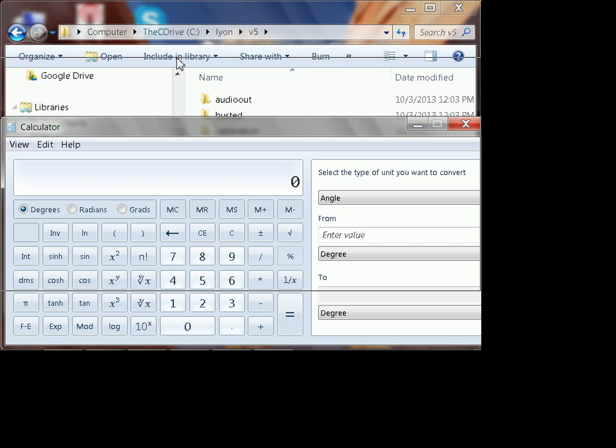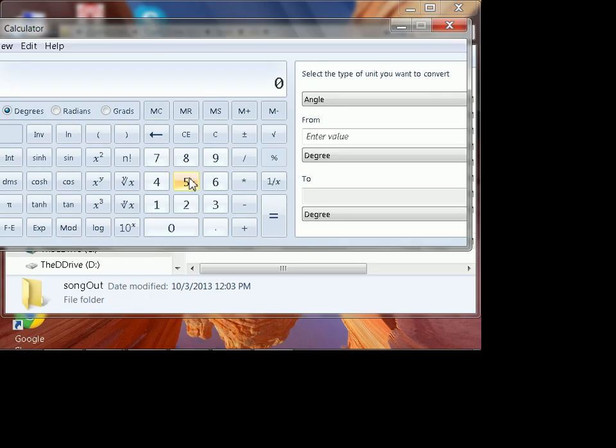Let's break out our calculator. 5 volts divided by 2 to the 8, which is 256, is equal to 0.019 volts. Multiplying by 1,000 to get millivolts, the minimum voltage the ADC can detect is about 19 millivolts. So a microphone signal going from 0 to 10 millivolts is generating nothing that the ADC can detect.